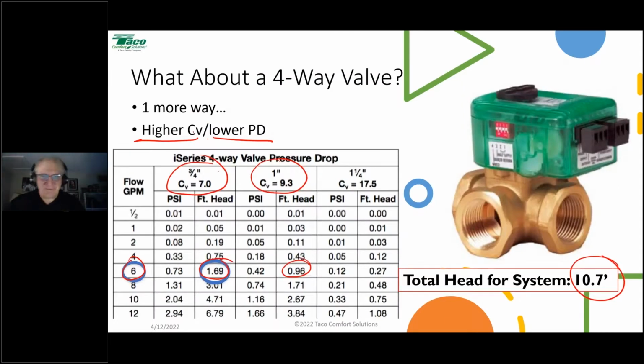Think about a 4-way valve, especially this. This is a reactive valve, meaning what it's going to do is it's trying to give you a water temperature, okay? It's trying to match the water temperature it delivers to the outdoor temperature. So as it gets colder out, the water temperature goes higher. As it gets warmer out, the water temperature goes lower. It's your outdoor reset. It's a motorized mixing valve. So that motor moves the flapper inside that valve to create the mix at a fixed speed, okay?